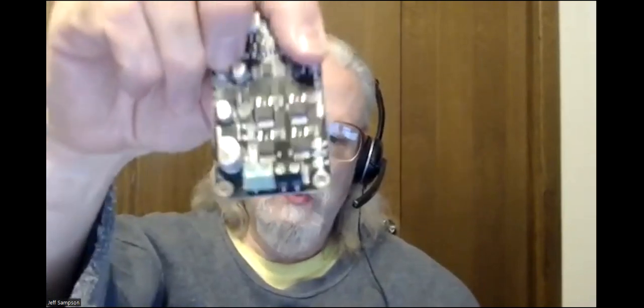So the advantage of these ferrules is if you've just got stranded wire sticking out, once you put these on, you don't have random strands of wire shorting out on things. And if you put them into terminal strips, like these, which have the little screw on the top, you slide something into that, you can put wire in there and crank it down. But for some reason on mine, all the stranded wire always seems to work its way out. So by putting these things on, let's see if I can get this to fit here.